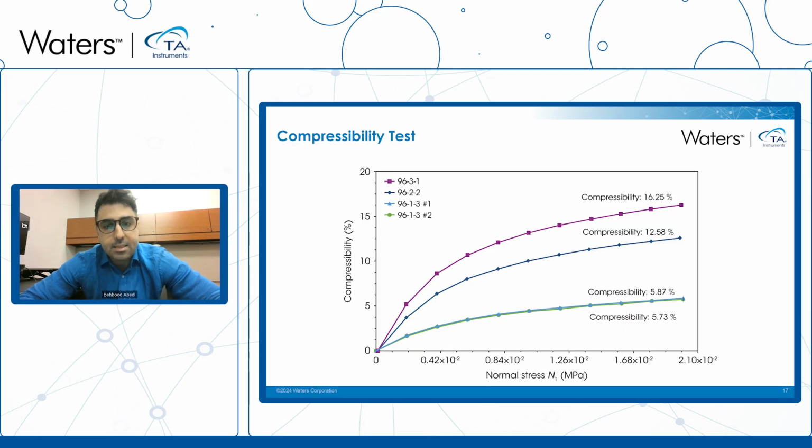And the reason is that carbon black has the highest surface area to volume ratio, so it can fill the voids between those NMC spheres that I showed you, so it increases the compressibility. And compressibility is a very important element for powder coating.